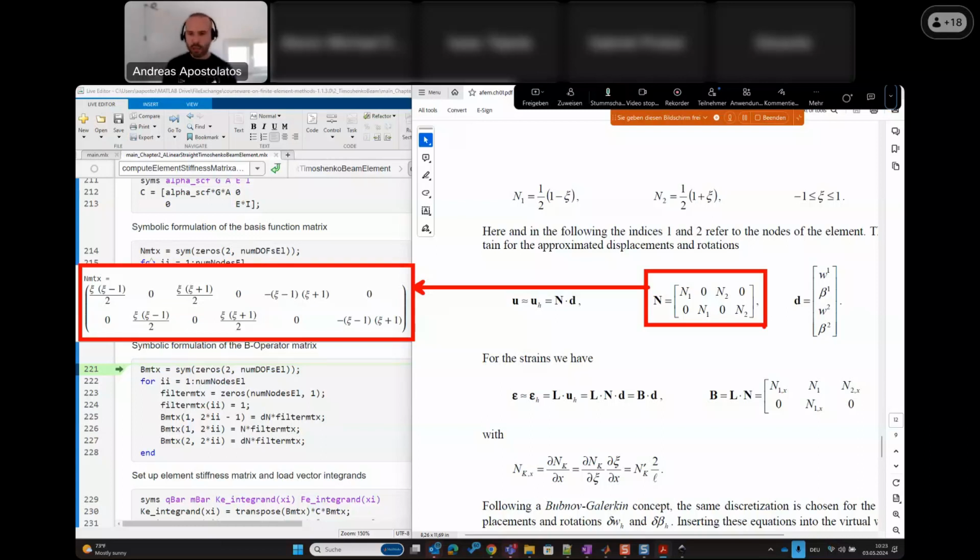So there is actually an additional basis function. We have here also the N3. So this is an N3, and this here an N3, and that's because in the script I just run the quadratic ones, right? In the computational script, in the static PDF, the script only contains the two noded elements. I use also exactly the third ones. So it's the same thing. If you have a quartic or quintic or whatever else, this matrix just carries on expanding. It's no difference, right? It's carrying on expanding. That's it, basically.